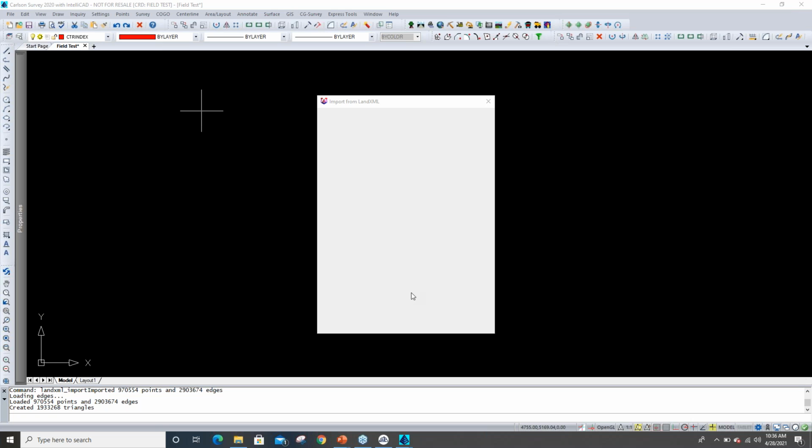So the next dialog will come up. It will let me do a few more controls. You'll notice there is an edit button that has some controls for doing things like break lines. In this case, I don't have any, so I'm not going to worry about it. I'm just going to go through the regular contouring dialog box and select my normal standards or my normal defaults. So if you use a CAD program for contouring or for mapping purposes, you can use your same set standards or the same normal defaults that you have to create contours from this data.